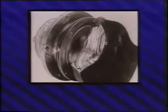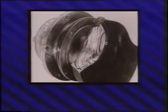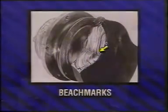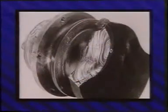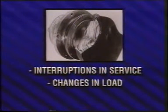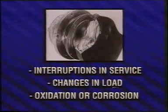The most common macroscopic feature characterizing many, but not all, fatigue fracture surfaces are the beach marks. Beach marks are centered around one or more sites corresponding to the fatigue fracture origin. When present, beach marks provide valuable information: the point of origin, the relative load intensity, and the crack dimensions at final failure. However, fatigue fractures will show beach marks only if one or more of the following factors were present: interruptions in service, large changes in loading magnitude or frequency, or oxidation or corrosion of the fracture surfaces during rest from intermittent service.